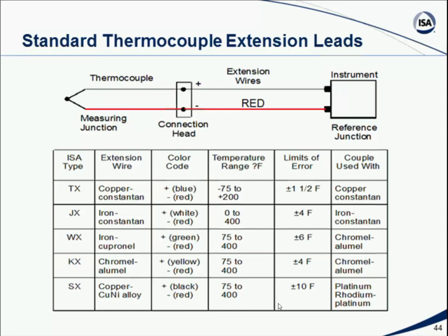Now, thermocouple extension wire isn't cheap. And in fact, if you have a long thermocouple run, it's kind of a pain in the butt. But as we had mentioned with RTDs, today it's far more common to keep our thermocouple run very short. It's far more likely that we'll use a smart thermocouple design where the thermocouple itself is again mounted inside a probe that sticks into a vessel somewhere, and at the head of that probe we'll put the electronics right there to measure the voltage from the thermocouple and convert it to a 4 to 20 milliamp signal or some other type of signal that's transmittable, and eliminate the need for this expensive extension wire.